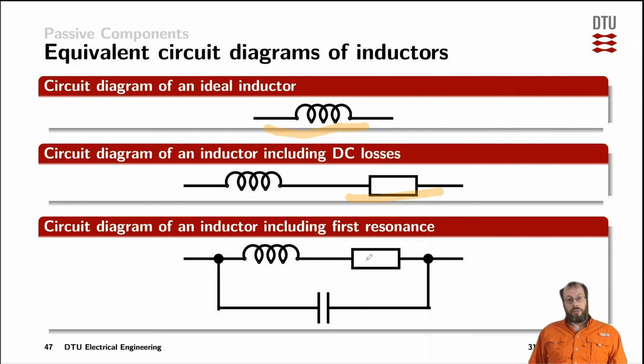And then on top of that comes even worse. Every inductor comes with, in second approximation, at least another capacitor, which is in parallel to the inductor. If you would model even more precisely, we would actually add even more capacitors to your original inductor that you wanted to buy from your favorite distributor. But you can't get it without the resistance and without the parallel capacitance.